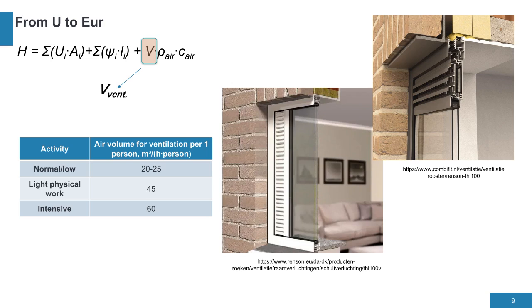replaced during 1 hour. In the case of natural ventilation, air enters the building through opened windows and doors, outdoor grills, and vents, and leaves through ventilation stacks or also opened windows and doors. Natural ventilation occurs due to the wind's impact on the building and the density differences between warm and cold air, which cause the air to move.